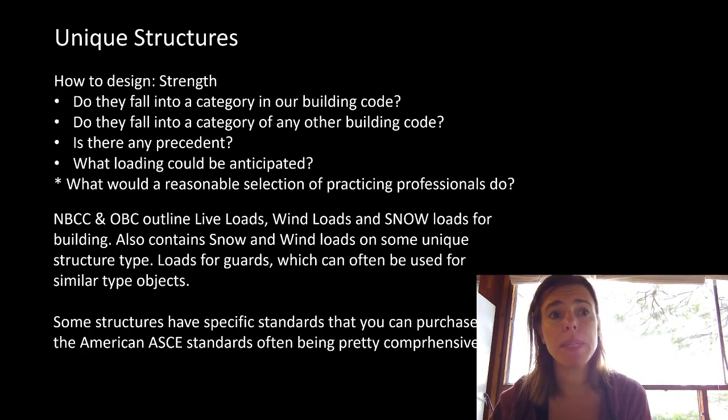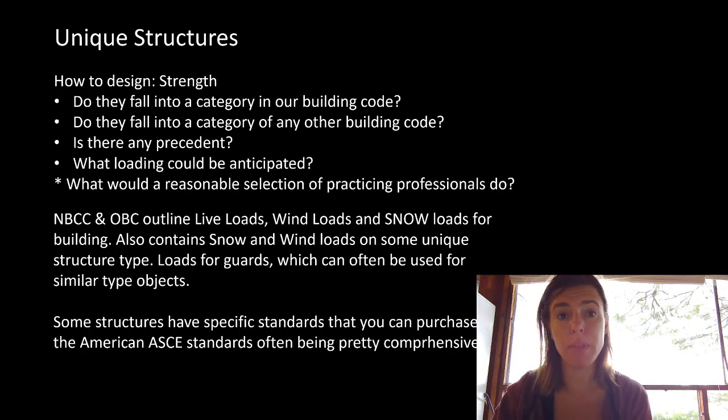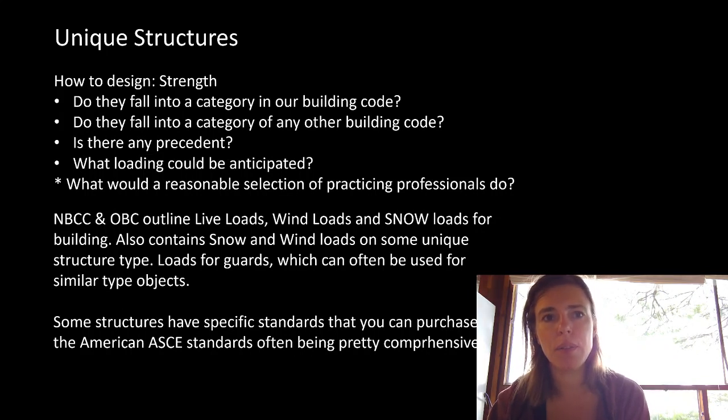Some types of structures have specific standards that you can purchase. The American ASCE has a lot of standards for playground equipment, for example. They have very specific playground equipment loads codified that can be pretty comprehensive. I have, for some things, purchased these codes, and it just says, oh yeah, use the building code loads, which was a waste of $100 for that particular code, because I literally already had the building code, and I probably would have inferred that in light of any other code, would have just used the loads from the building code. So sometimes it's a bit of a rabbit hole that way, but you can usually come up with a good context for your design loads.